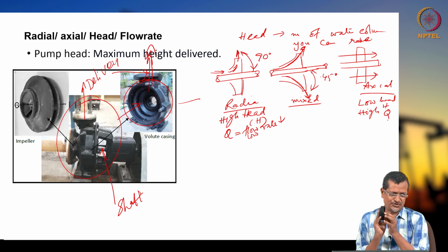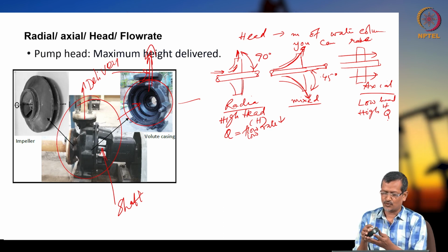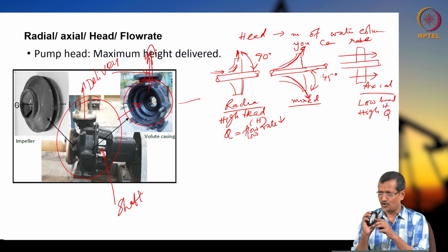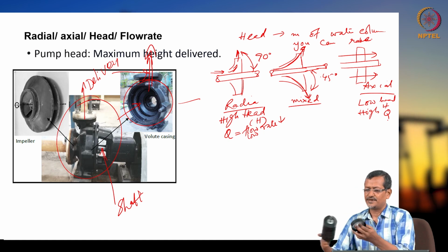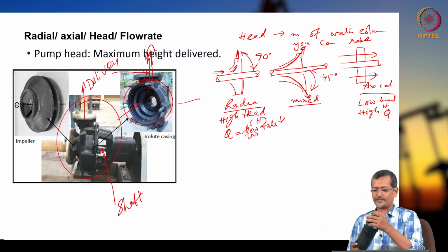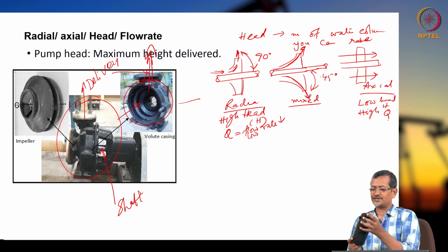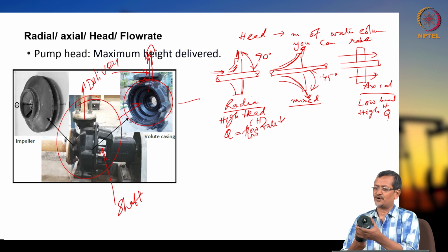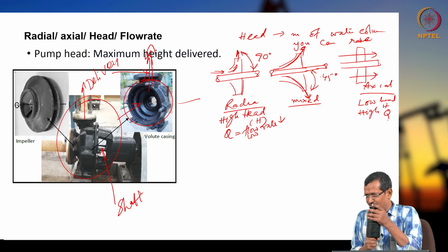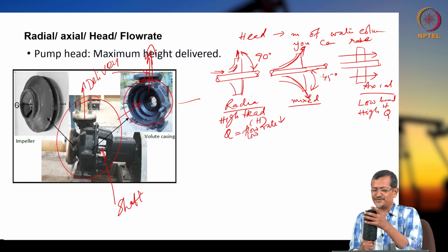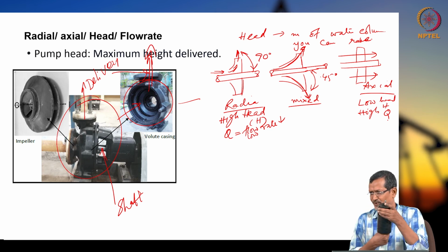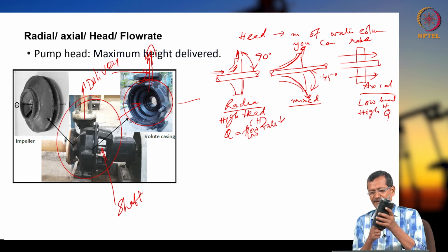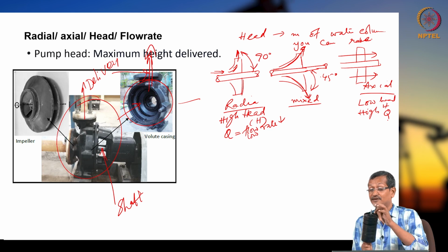and it becomes one stage, one rotor. This is called the rotor, rotating, and the stator or casing is not rotating. This will be fixed on this one. If I put it here, the shaft can rotate my impeller. The shaft can rotate, but my casing is not rotating. The casing will be fixed on a separate pipe, so that's why this is the stator. Stator means the casing part not rotating, only my impeller rotating. The shaft rotates only the impeller, that's why it is called the rotor.